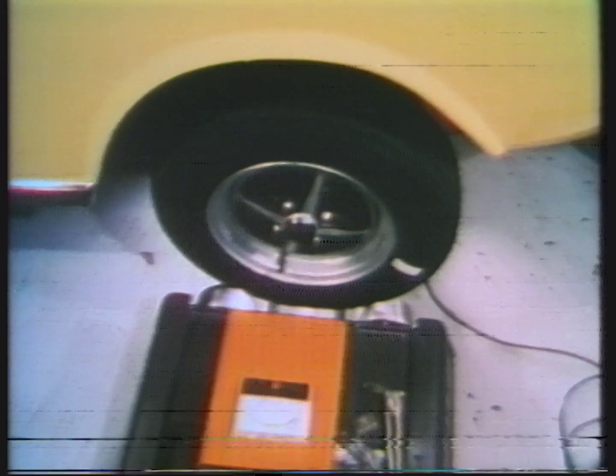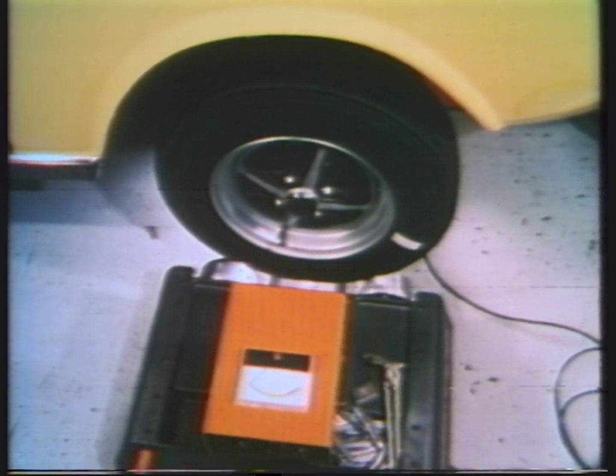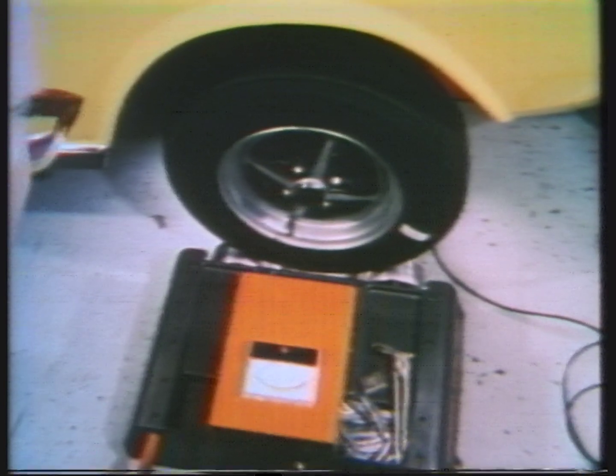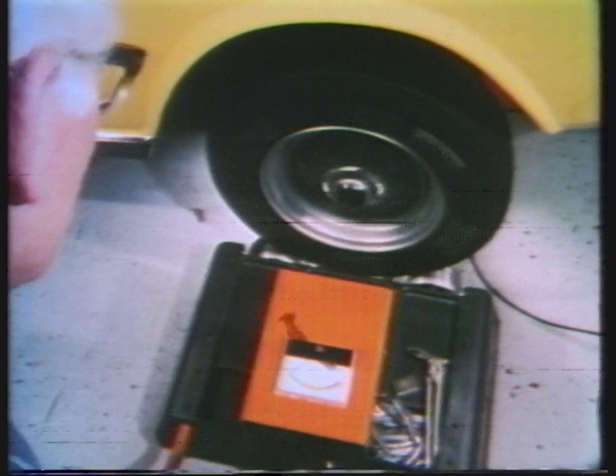Returning to actual wheel balancing. Having fitted the balance weight, always check that balance is within limits. And make sure the job is right at the time you do it, while the equipment is still set up. Then you never have to come back later if you hit a snag, just in case.